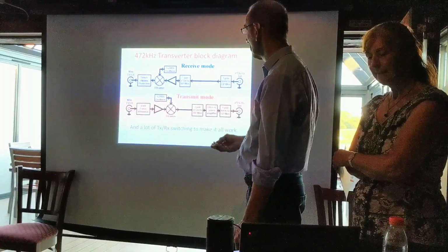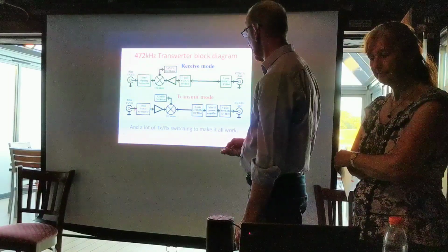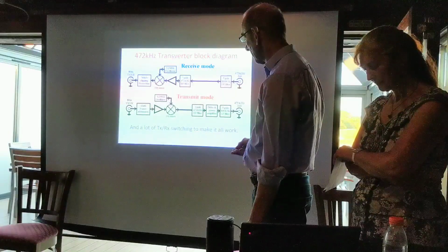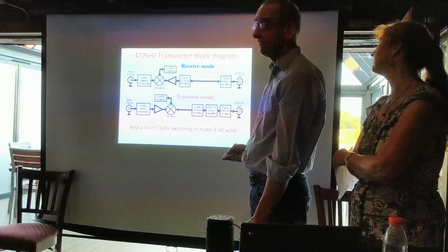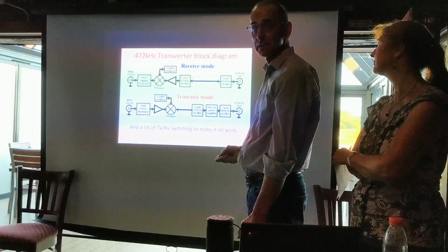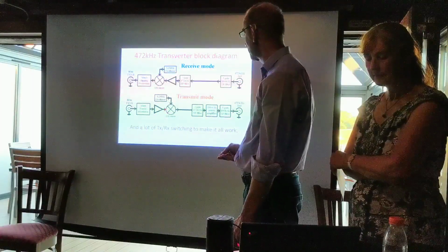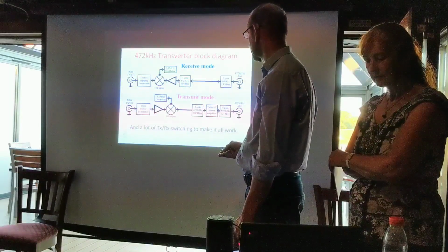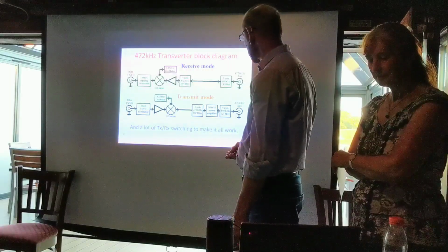As we've said before, in the transmit mode, we come in through a power attenuator. Now, the mixer chip already has a big amplifier on the front end, and you can't get rid of that. So I've actually had to attenuate the signal more than I would have otherwise done, but it doesn't really matter, it's easy enough to attenuate stuff. We then mix it with a local oscillator, 3.2 megahertz, you'll see why in a little bit. It goes into the mixer.